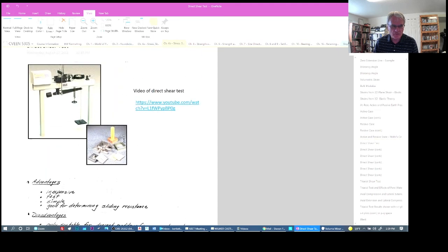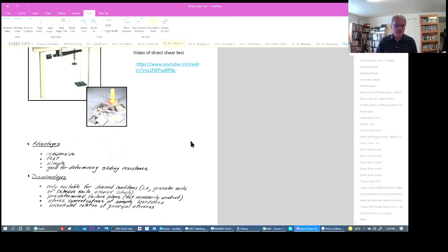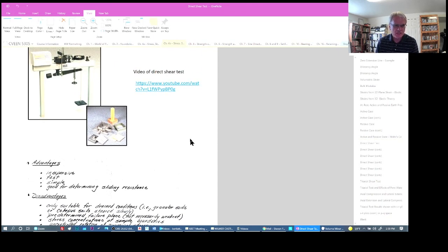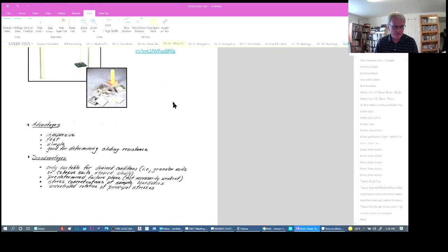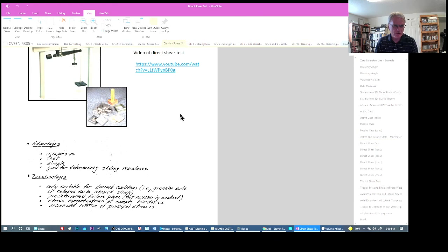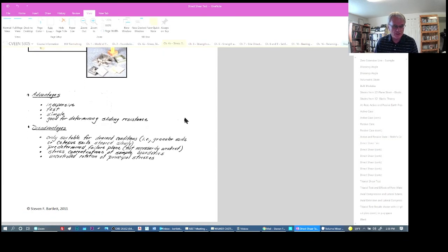Next, let's just talk about the direct shear. I've talked already a little bit about this in class and how the direct shear is done. If you'd like to watch a video, I've included a link here for you that you can go in and look at that test. And just some advantages of the direct shear test is it's inexpensive, it's relatively fast, it's a simple test, and it's good for determining sliding resistance along horizontal planes.